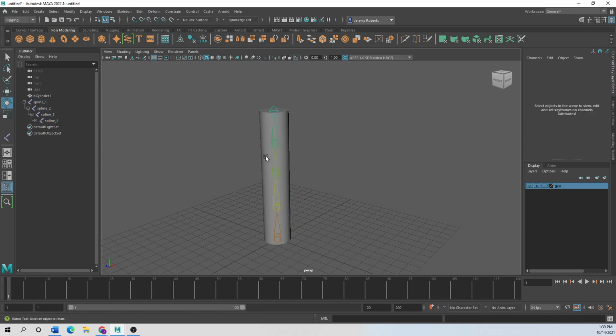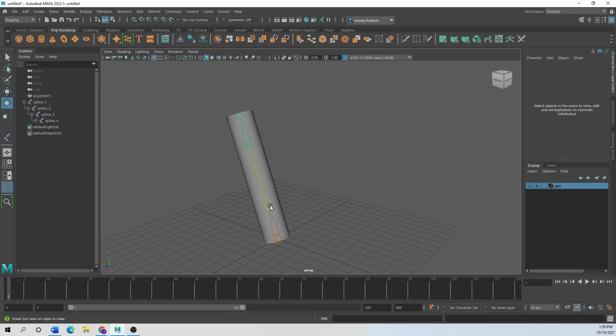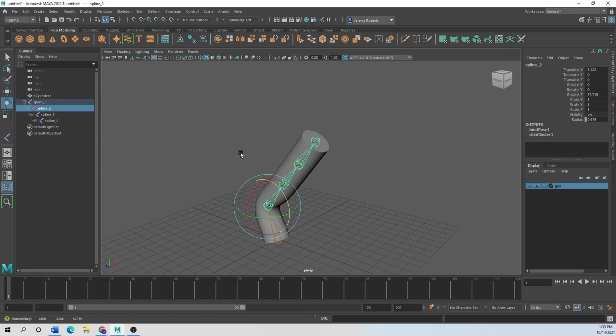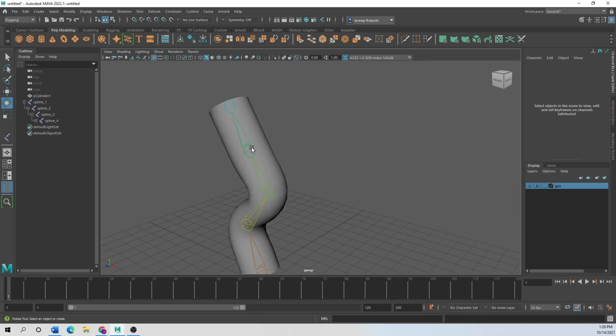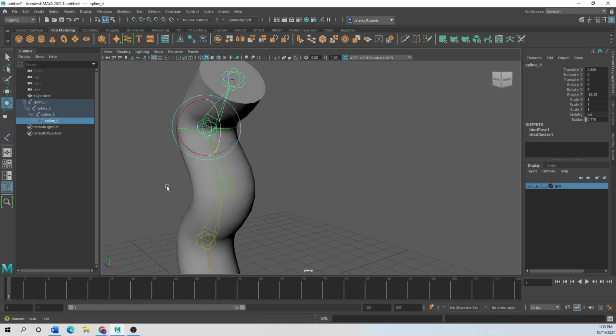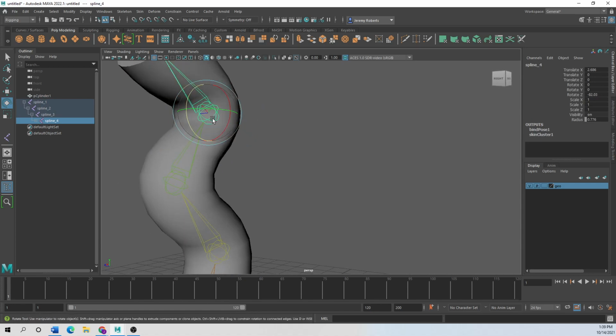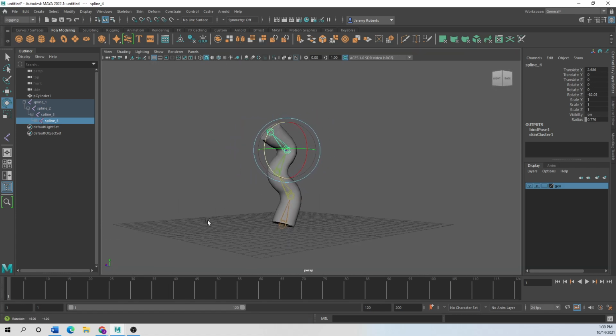That made them change different colors, and we'll get into painting weights basically with the joints. But if you notice, now as I start moving these joints, the geometry is actually kind of weighted itself to the actual bones. And if you do this first off, if you have some weird bends in the geometry, don't fret. That is common because you have to go in there and kind of paint these vertexes to start not tearing as much whenever you move the controllers.